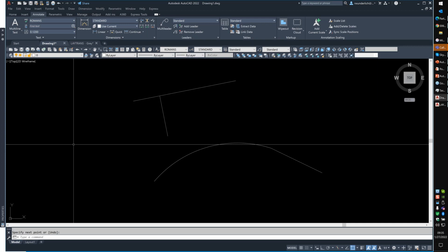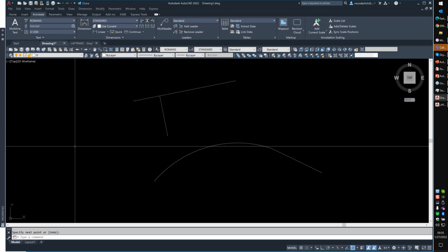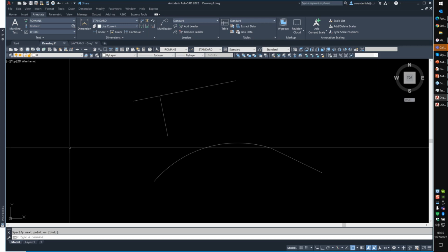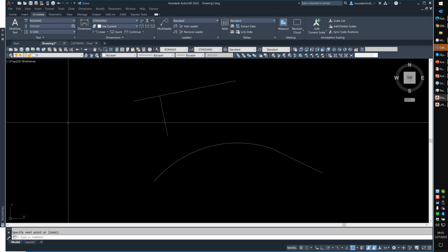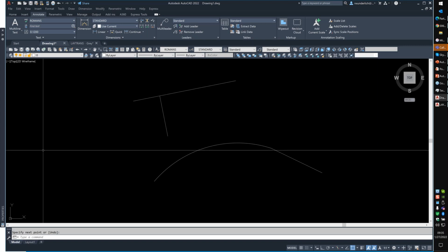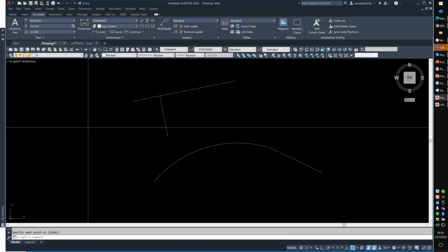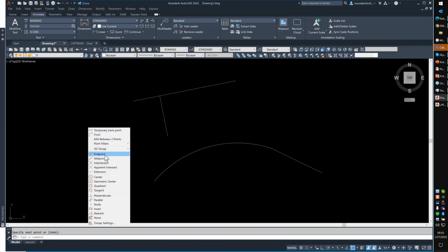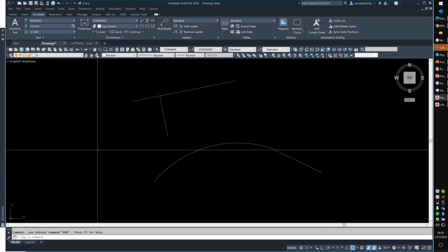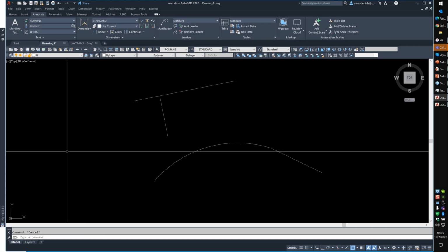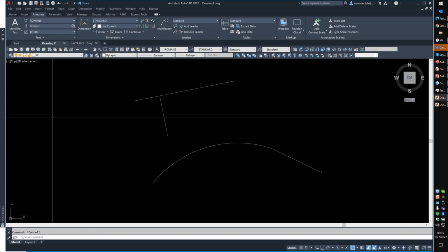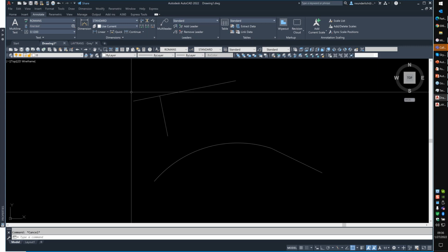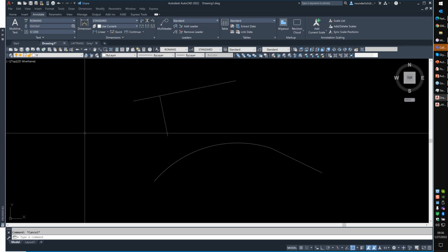There is a way to do it. You have to go in and modify the CUI and put the emphasis on the N. You have to change that from none to nearest. So when you do this shift right mouse click, you're going to see N defaults to none. There's a way to do that, but it requires modifying your AutoCAD CUI, and then it's only modified for you.